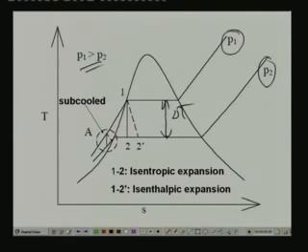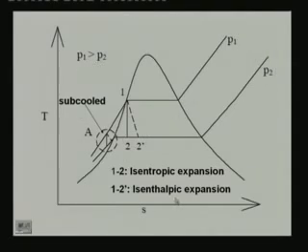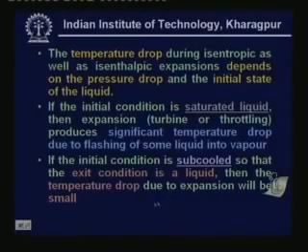You can see that the temperature drop is significant as long as the initial condition is saturated liquid and the final condition lies in the two phase region. As I said, if the initial condition is saturated liquid, then expansion produces a significant temperature drop due to flashing of some liquid into vapor.